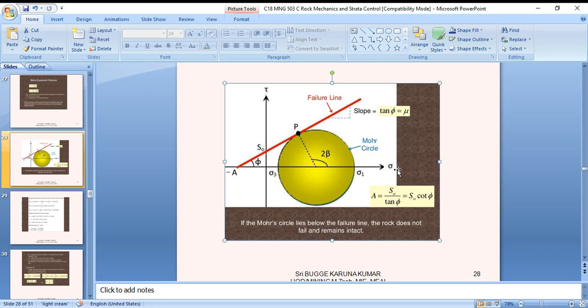It is necessary that the scales of these two axes are equal. Plot the normal stresses sigma x and sigma y on the normal stress axis. The shear stress tau xy acting on the right hand edge of the element is plotted directly below or above the point representing sigma x on the normal axis.